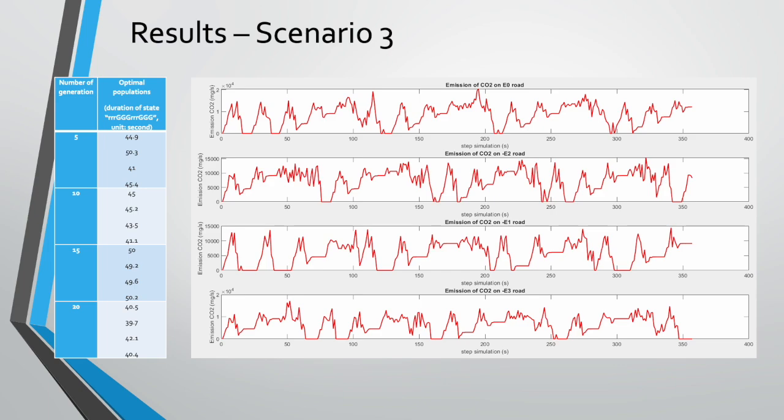While the travel time graphs exhibit clear plateaus, representing static queues during red phases, the corresponding CO2 graphs show a more volatile behavior. Notably, the most severe pollution spikes do not occur during the peak delay, so during idling, for example, but rather during the transition phases when the signal turns green. This indicates that the acceleration inertia of the discharging queue generates significantly higher instantaneous emissions than the static wait, highlighting a critical trade-off.